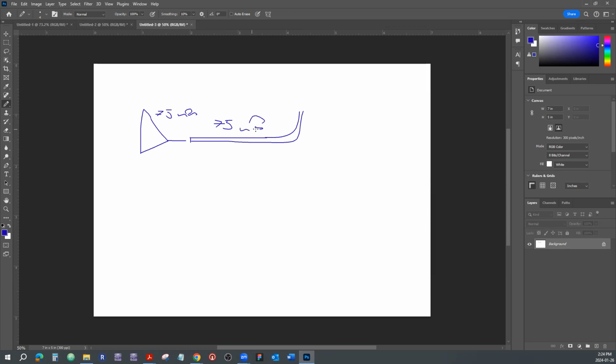Now that is going to be connected to an antenna that will also have 75 ohms impedance. So here is the output impedance of the amplifier, the characteristic impedance of the cable, and the impedance of the antenna. We have the same amount of impedance. The impedances are matched.